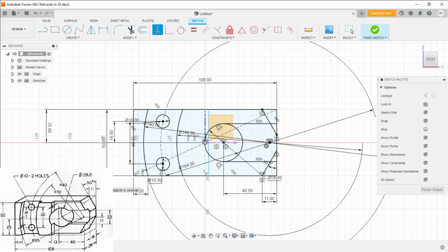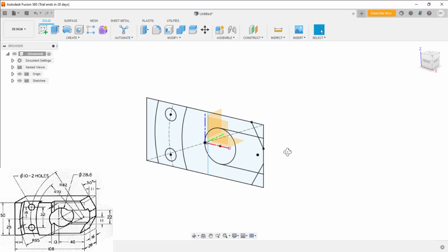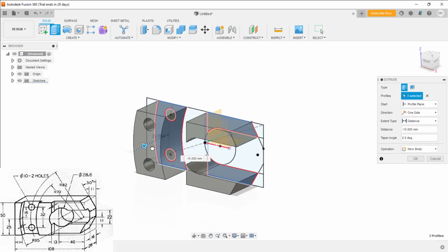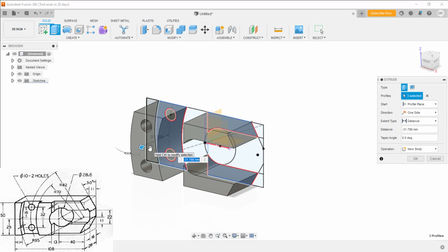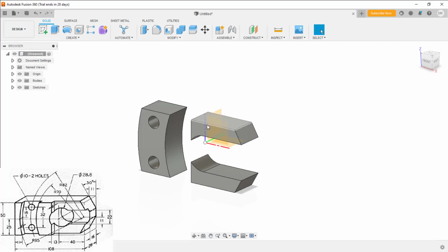Yep. So here in other software like SolidWorks and all, automatically the relations will be snapped, but here it does not. Might be in future they might change it, or else if this is fine for them, that's okay. Yep. So I'll use the push pull, only these contours, drag it up to the dimension, minus value you need to enter, it is 28 minus the value 6.